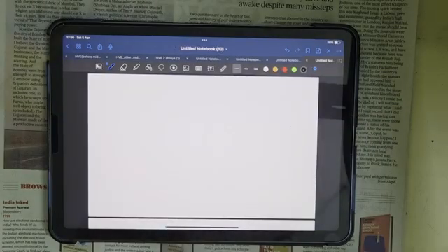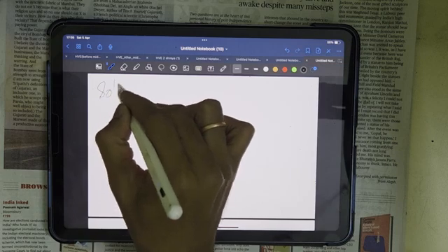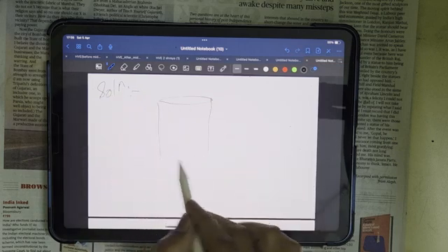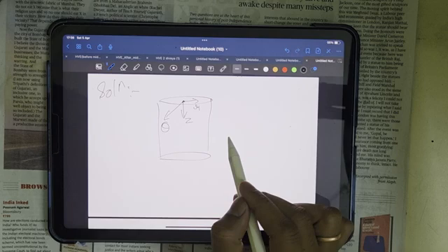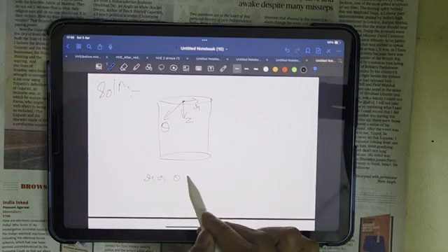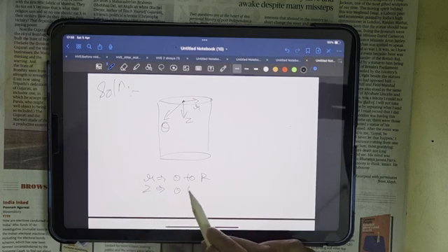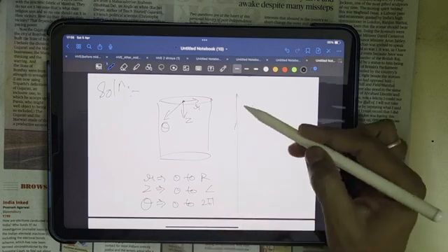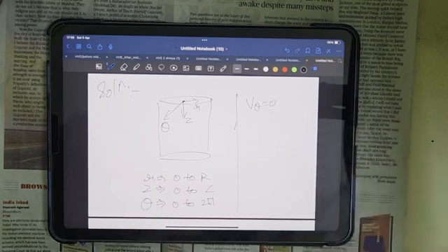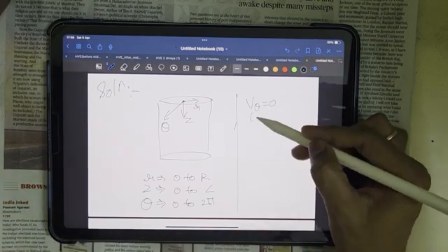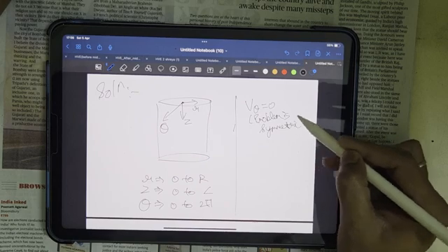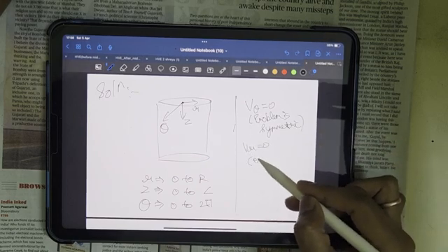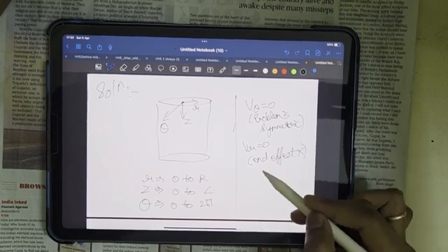So as we have discussed the problem, now we will look into the solution of the problem. We will choose cylindrical coordinates for the problem. The directions are r, z and theta. R varies from 0 to capital R, z varies from 0 to L, and theta varies from 0 to 2 pi. V theta is 0. Velocity in theta direction is 0 because the problem is symmetric around theta. Vr is 0 because end effects are neglected, and also the fluid is incompressible.